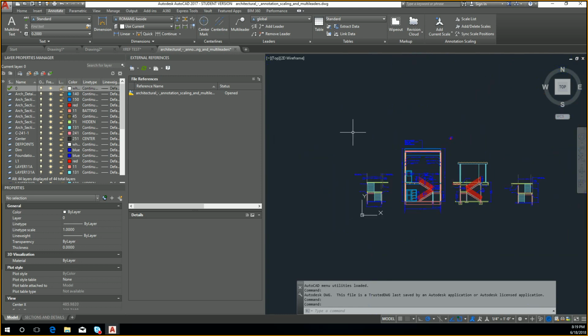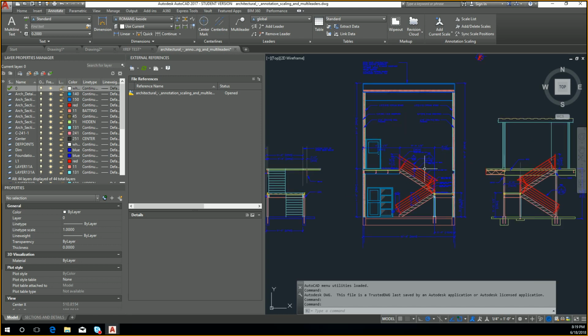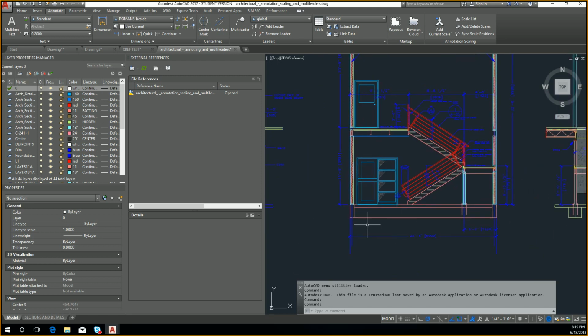So is that clear, the difference between inserting an object and creating a block within your model space and the external reference? So in most of the cases, you will use the attaching. It depends. It depends on what your goal is, right? So inserting a block allows you to directly modify something. So let's say this was a standard staircase of your type A building, right? Every building starts like this, and then you're supposed to go ahead and modify from there.